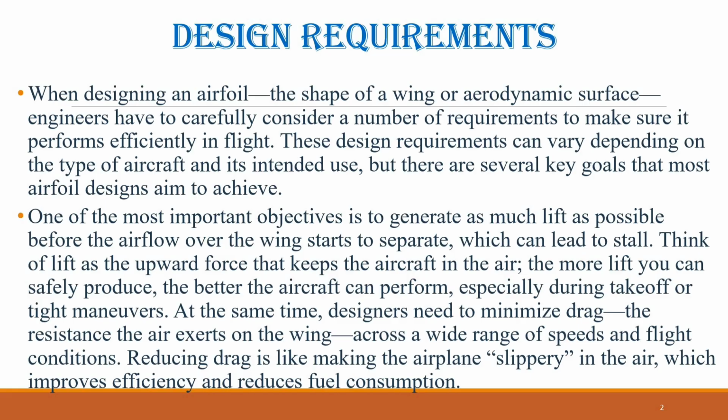Understanding how the boundary layer, the thin layer of air close to the wing, transitions from smooth, laminar to turbulent flow is critical for designing airfoils that perform well in these conditions. Even small design tweaks can make a big difference in lift, drag, and overall efficiency for low-speed UAVs.